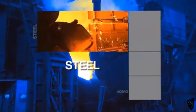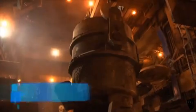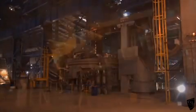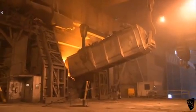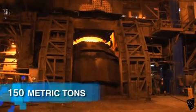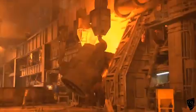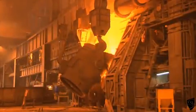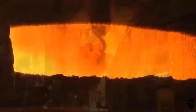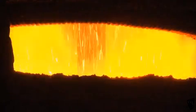For the conversion of pig iron to steel, AMSA uses the oxygen-based technique of steelmaking called BOF, Basic Oxygen Furnace, as well as an electric arc furnace. BOF steelmaking begins by loading scrap metal into the converters, pear-shaped refractory-lined furnaces with capacities of up to 150 metric tons lined internally with refractory brick. When the proper amount of scrap metal has been loaded into the converter, molten pig iron is added by means of large ladles operated by traveling cranes.